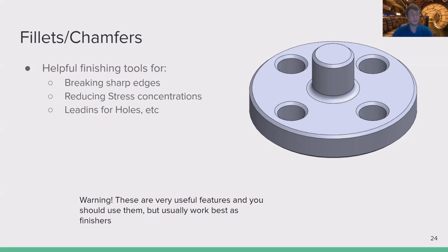Definitely recommend using them. But generally, you want to do this at the end of your part just to save yourself some grief. Usually these are kind of finicky features. So if you have them in the middle and then stuff changes earlier on, it can break. So just be careful with that. I'm sure at some point you'll have to deal with fixing it, and you'll get why I'm saying this, but just be aware.